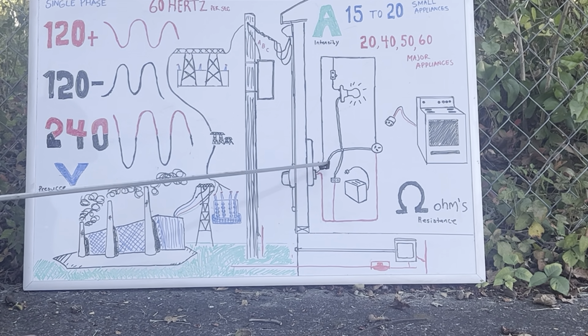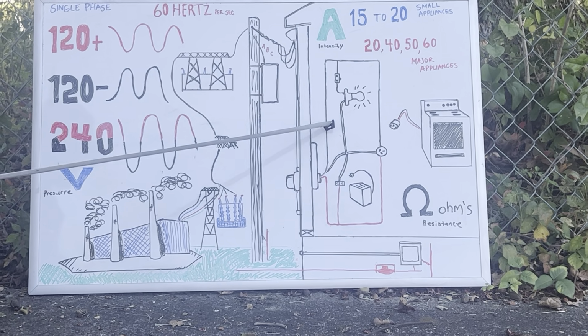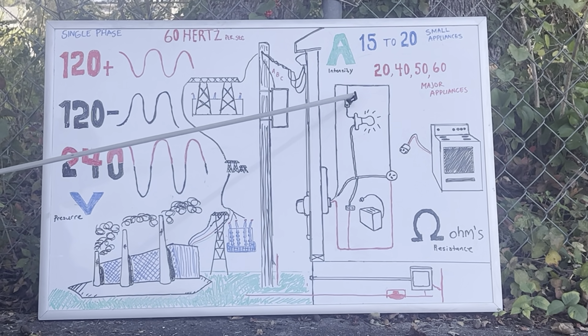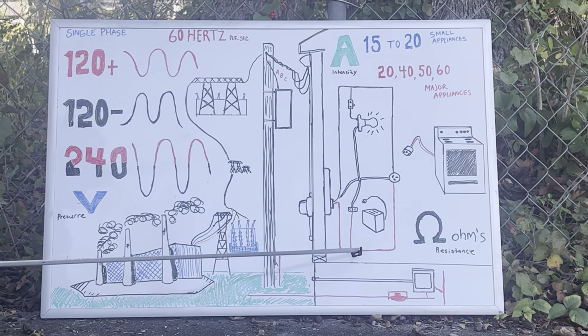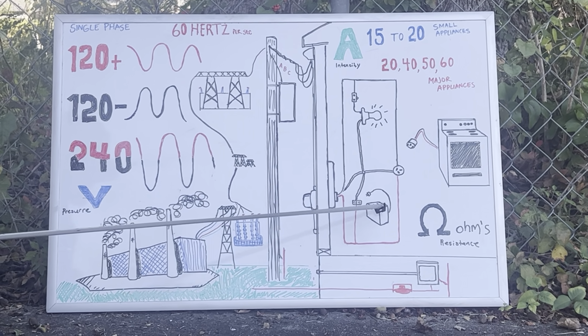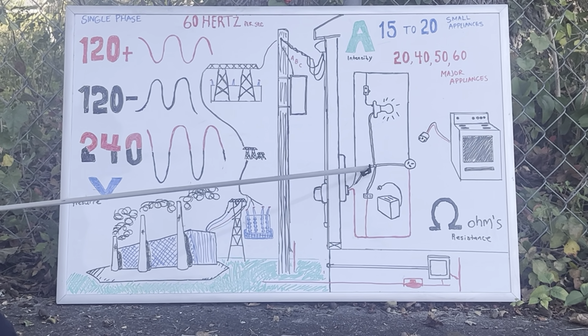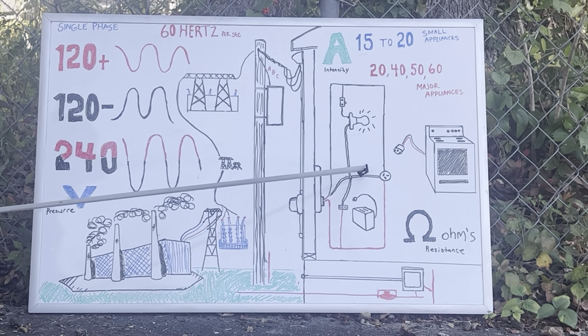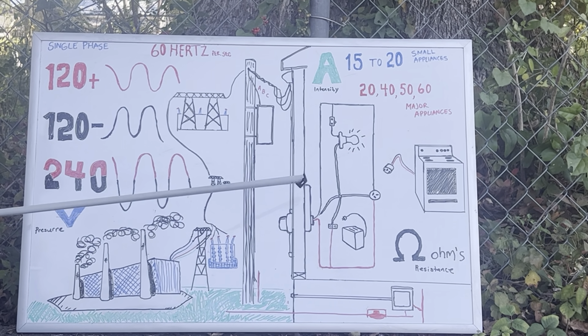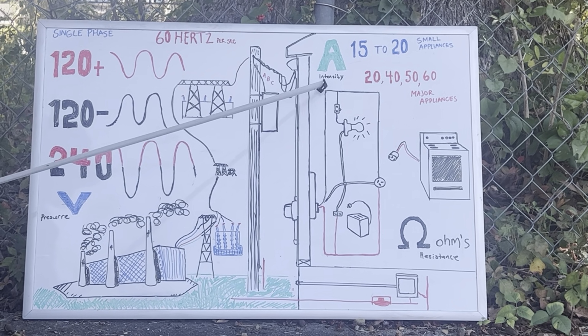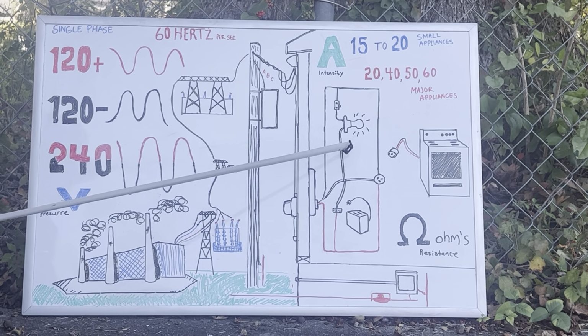Now you look at this circuit right here, and look here, this is my hot black going up here. You got it powering right here, my switch and my light. You got the red right here going this direction. I got a receptacle right here with my toaster. Now this middle wire, this is my neutral. So in order for electricity to flow, you gotta have a complete circuit. Right here, this is 120. I got my hot with my neutral right here.